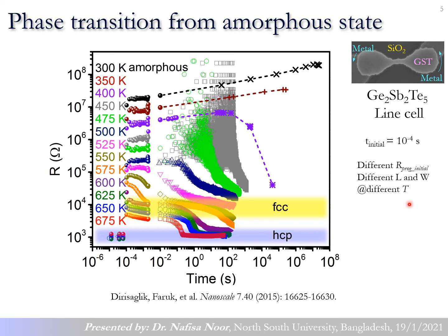So the retention time is defined in this way: how long it takes for the cell to retain the stored data. So when we store this cell as the high resistance state, we want this cell to stay at this high resistance state for a long time. So that is called the retention time. But this cell spontaneously is going to a much higher resistance and then going back to a lower resistance spontaneously, even at room temperature. So it takes about 10 years. So the retention time of PCM is about 10 years.